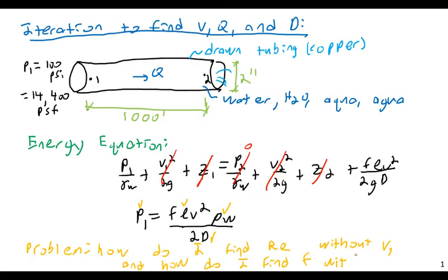This may be turbulent, and if it is, then we're going to need to use the Moody diagram, and then we need to know the Reynolds number, and quickly we're going to end up going in circles here. The issue with the Moody diagram is that it's a useful tool, but it is a diagram, in the sense that it's not a very simple input-output function. It's a chart. It's a tool. To borrow a term from grade school algebra, this is not a function that passes the vertical line test.